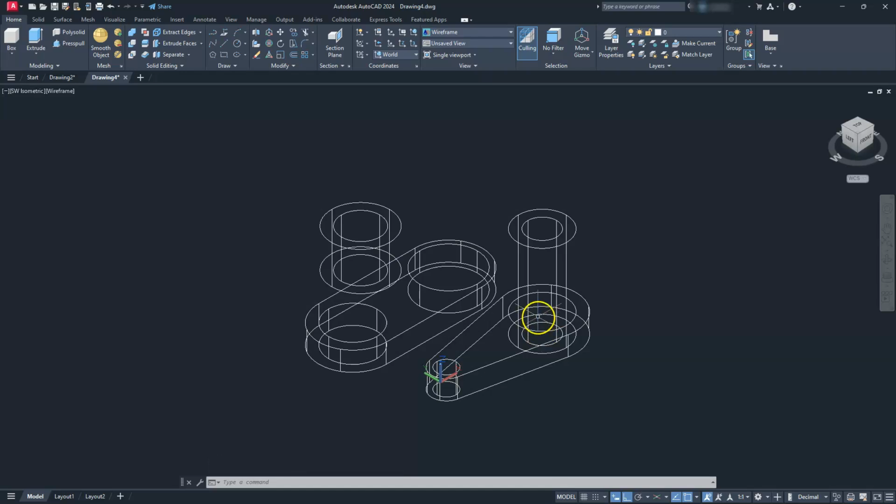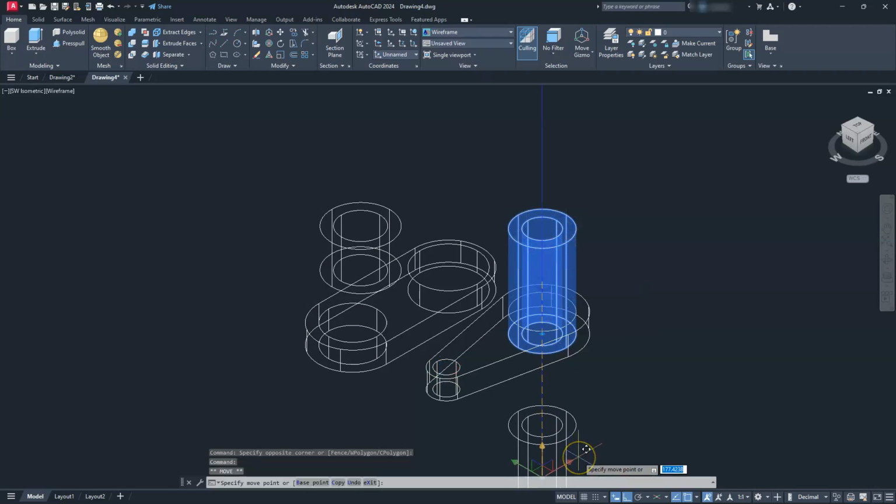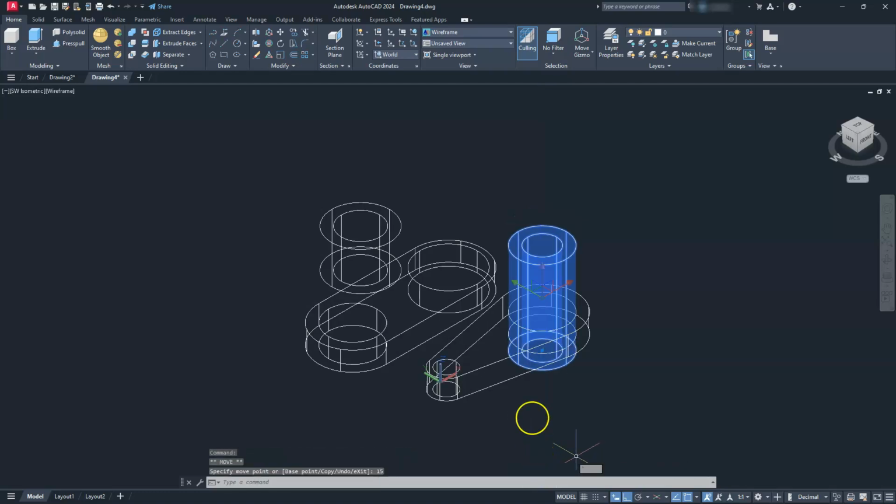So now we have that cylinder created where we want to create it. Now I need to move either the cylinder down or I can move this part up. In my case, I think I'll just move this cylinder down. So I'll select this cylinder, I'll select this axis here, I'm going to aim it downward, and then I'm going to type in that number that I need, which is going to be 15 going down that way, right? So now we've basically located our first piece.